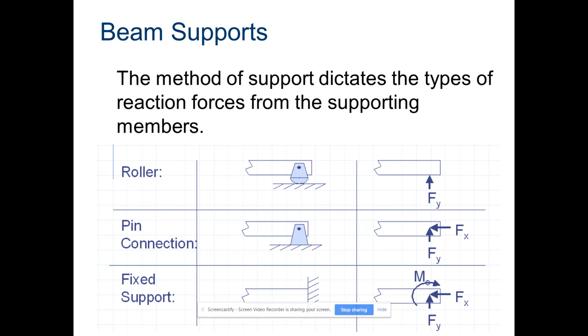So for a roller connection, you see there is only one reaction force. Okay, that goes perpendicular to the support, right? So you see Fy, one reaction force. Now with a pin connection, we have two, horizontal and vertical.